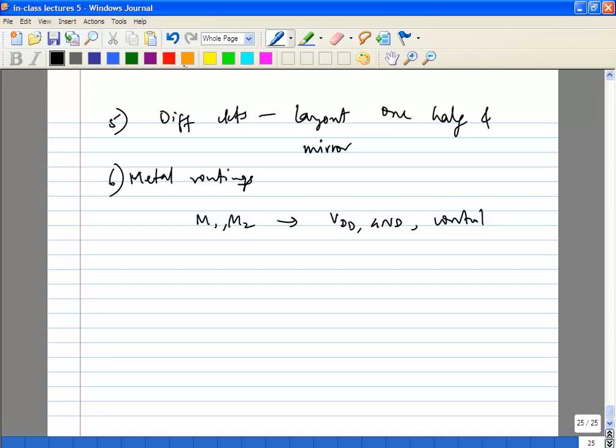You probably want to do, for example, substrate contacts, they all contact, you have to use M1. So at the lower level, as long as you don't have to route a long way, you can use them for VDD and ground. But definitely if you have control lines, power on, power off, or like gain control, those kind of things, you can choose to do M1, M2, and M1 and M2 also to some extent.